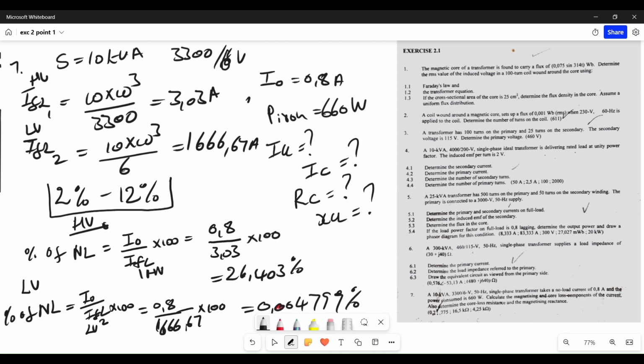But what I realize is that I cannot operate a transformer at 0%, because for the LV side this is 0%, meaning there's no flow of current at all. I can't operate a transformer on no load with 0%. But what I know is that I can operate the transformer at overload. It's not healthy for the transformer, it puts it under pressure. It destroys the transformer, but not immediately, only with time.